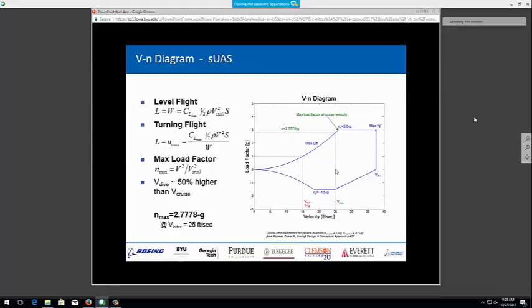I wasn't really satisfied with that. So the first step: the thrust is not really constant. We know that that's not true. We know there's a thrust decay with velocity. As you increase your velocity, your thrust goes down with our fixed pitch propellers. So I built a couple of MotoCalc models for representative sizes. These are based on Hacker motors that we've used in the past, a Hacker A30, 30 millimeter can, 40 and 50, and those are different sizes. And the static thrust varies from 4 to 12.5 pounds here.